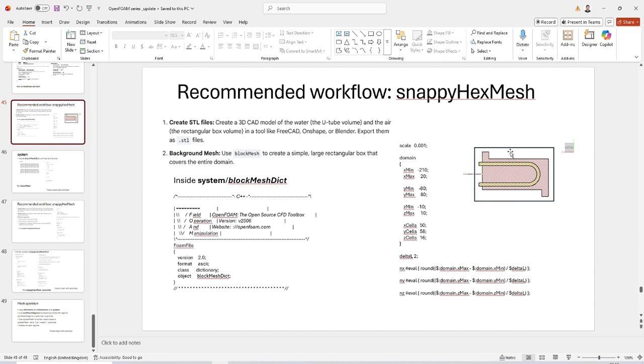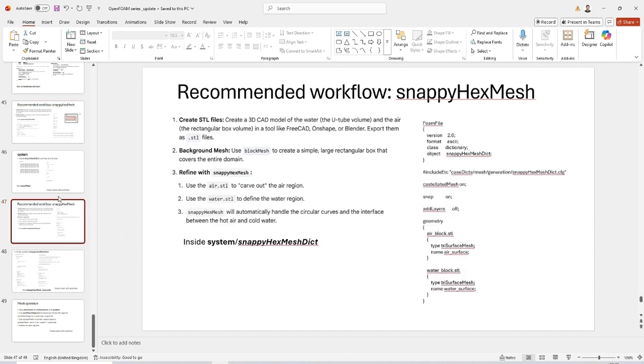If you are interested in the outside, you can put the mesh point here. If you are interested in the STL file, you can put it here, because sometimes we just carve this out, right? And want to use the left region. But now what I'm interested in is the STL file itself. So that's why I use the region inside the STL file.